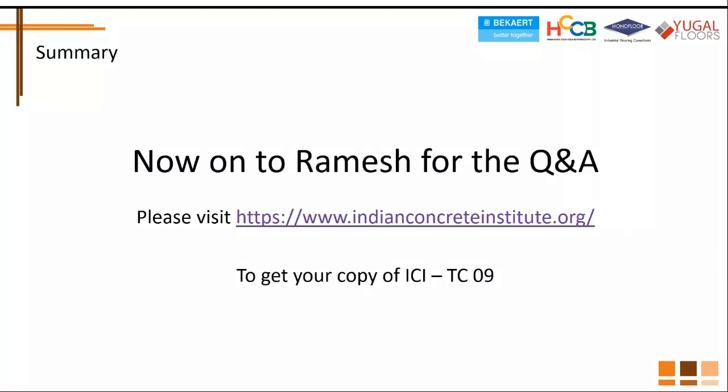Cannot be done. I would just like to add a bit here to what Piyush said. Also refer to the IRC guidelines because it clearly mentions what the plasticity index and the liquid limit of the soil should be. It would not harm if you already do this test on the soil that you want to fill in, to be able to justify using it as a material for the sub-base.